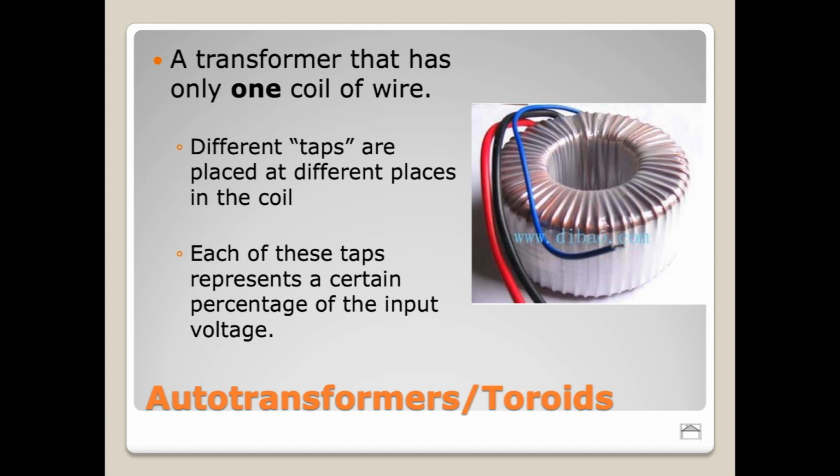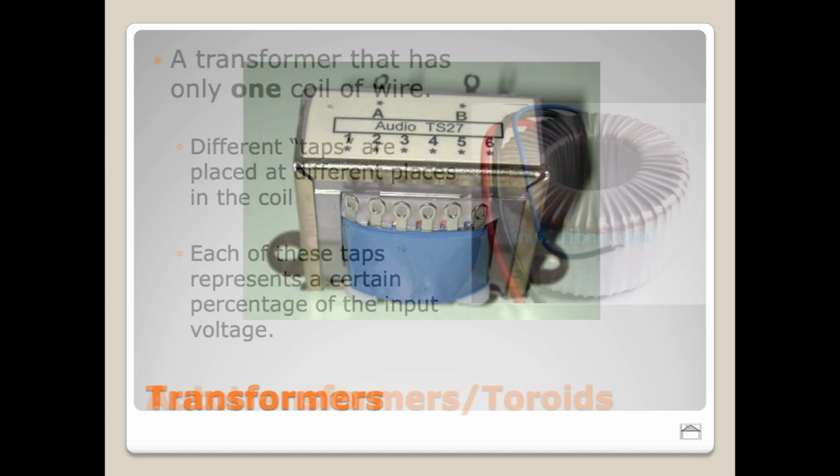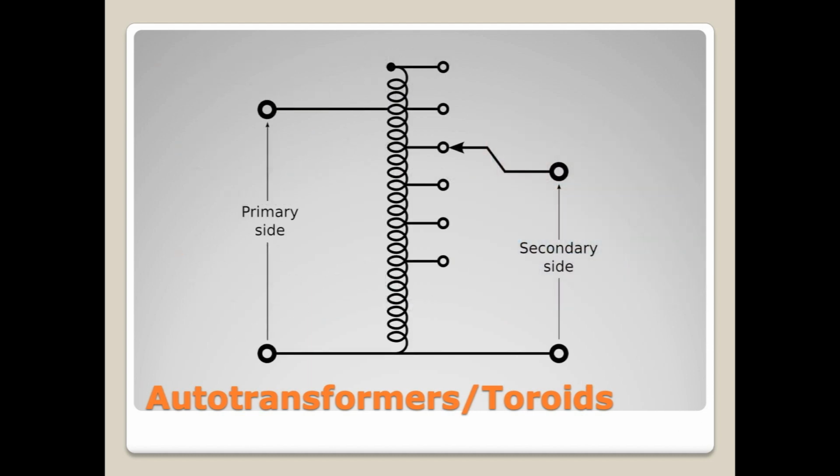If we have a big enough power supply, oftentimes they are separated from the device to make this an even lower probability. But if we have to have the transformer in the power supply in the device, toroids are often preferred for a variety of reasons. But you will see both. I see a lot of these EI lamination transformers in guitar amps, and you see a lot of this more in rack-mounted gear. So let's refresh ourselves real quick on the schematic diagram here for an autotransformer.